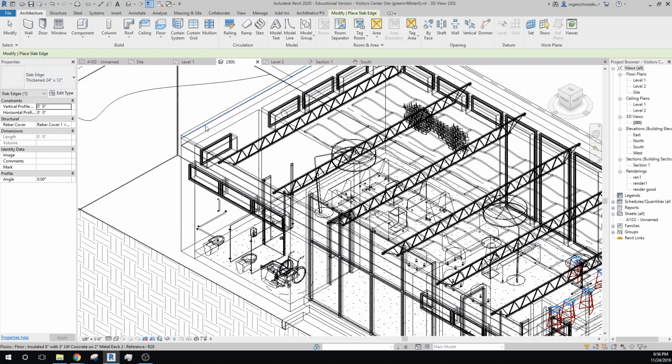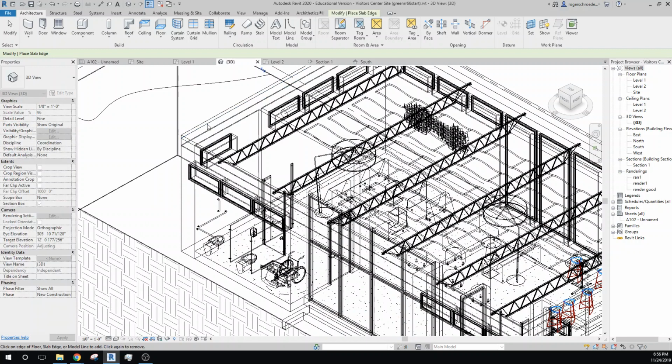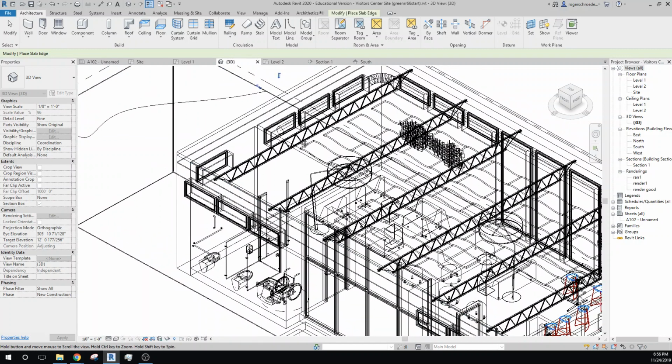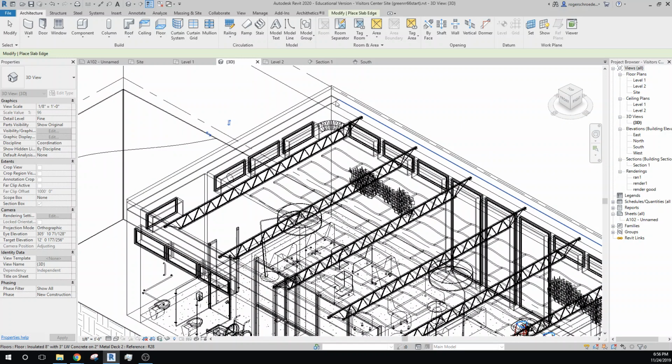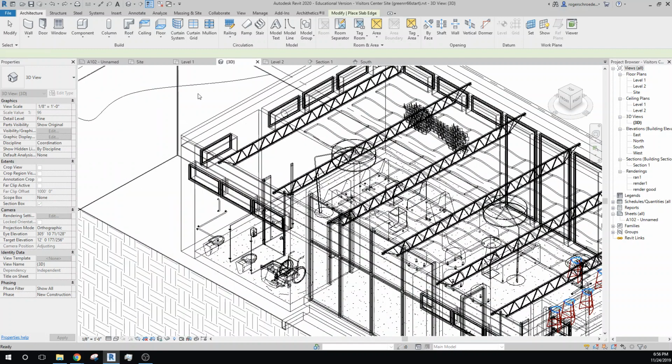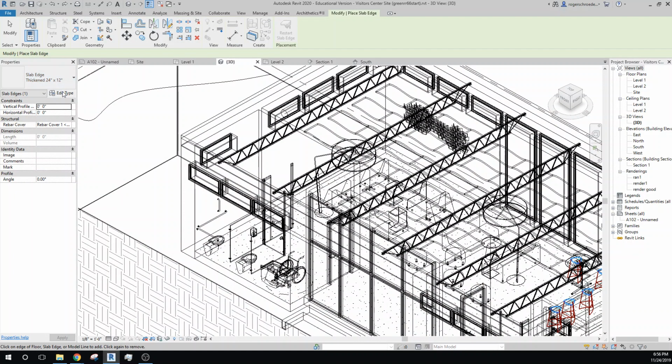And if I select that, it'll allow me to click on the very top edge of the floor and click on that. It'll make a floor slab embedded within the concrete frame. And you can't really see that now. It's just a thickening of the whole slab, but there's a profile in there. And we don't really want to do that. So I'm going to do Control Z, and I'm going to edit this type.